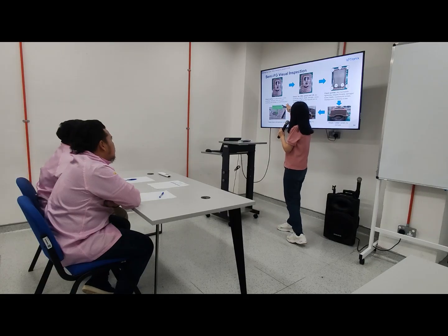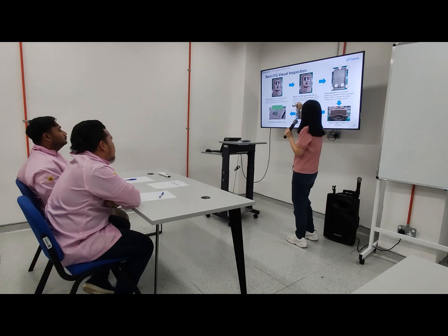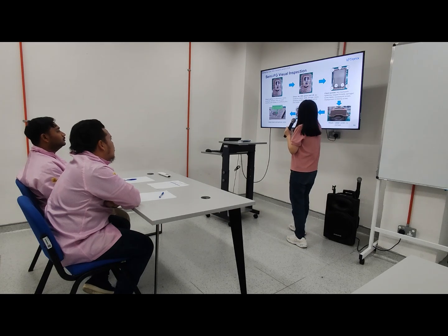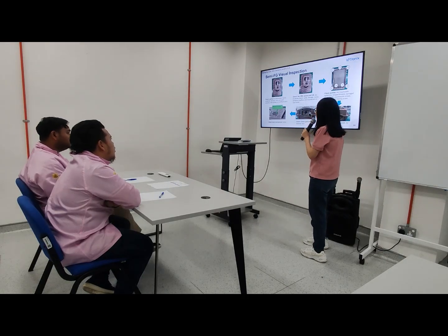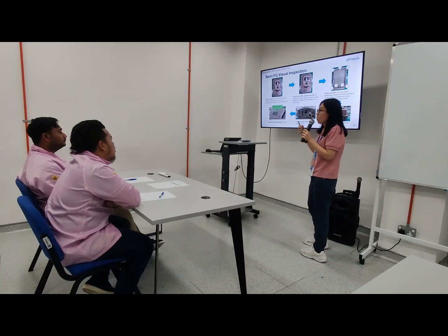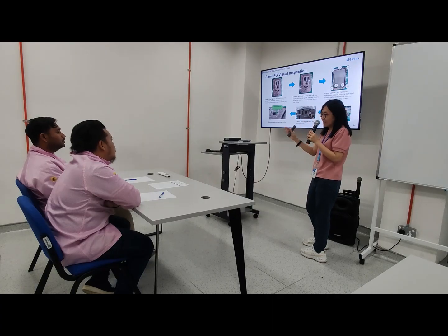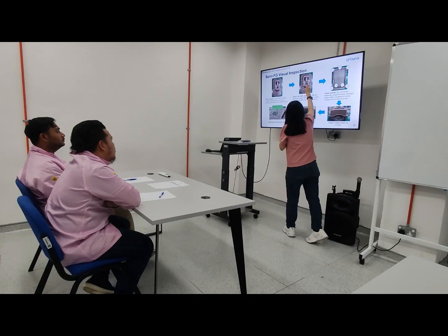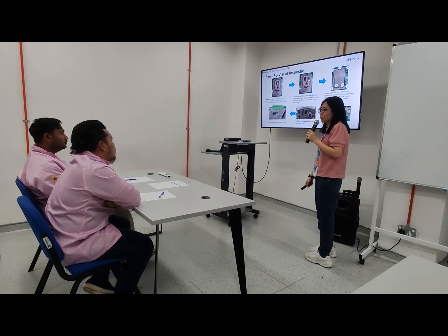Okay, after the casing, we go on to check the lens, the PIR, camera, and IR. All of these. We also check for any scratches, stains, spots, damage, cracks, adhesive overflow, or exposed wire, and most important, make sure it is clean. Especially this camera, make sure it's clean because we need to capture photo and video.